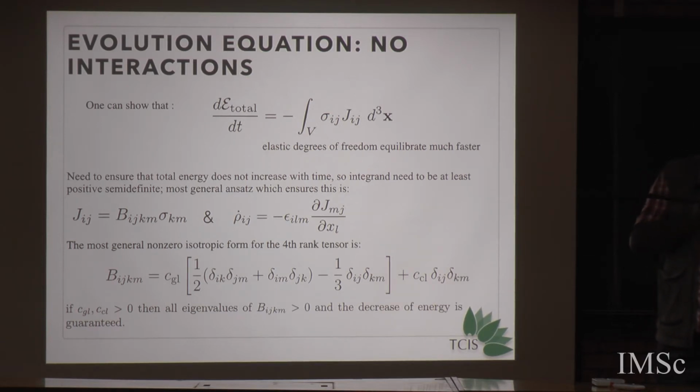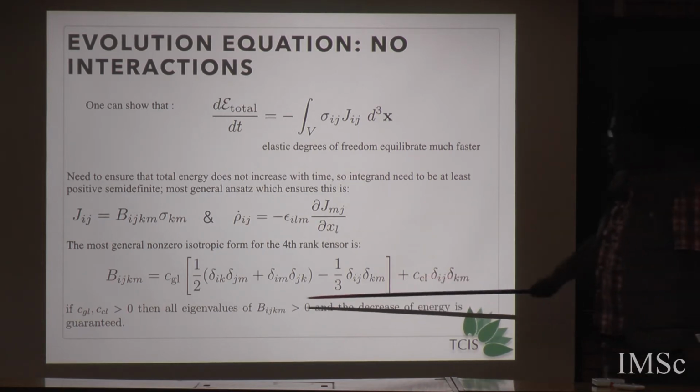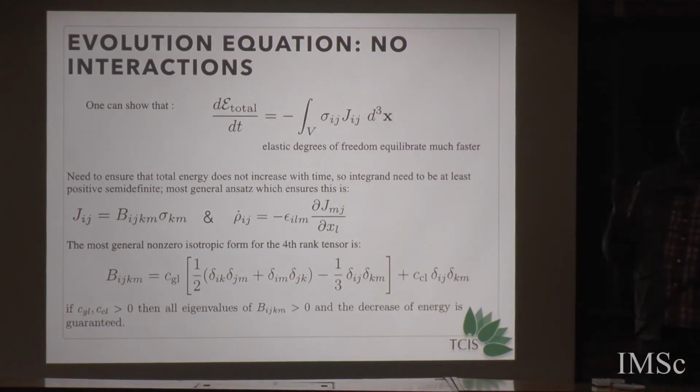The Burgers vector and the tangent t define a plane. If the velocity is in that plane, then it is glide. If it is out of this plane, that would be climb. So one can show that these are nothing but the coefficients of climb and glide. So how much climb and how much glide?